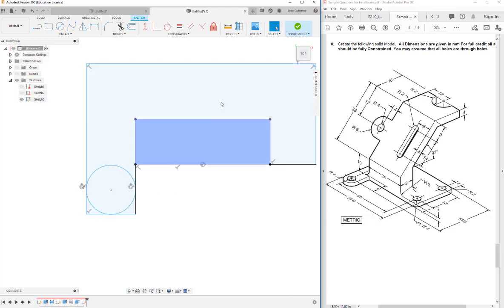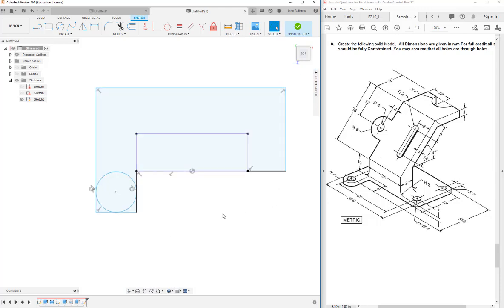It doesn't have to be perfect to what you want to extrude. And actually what we'll see is I'm not going to sketch these corners. I'm going to add those as fillet features after the fact because dimensioning those is going to be too much of a pain. Okay, so now I can dimension this circle again. Now since this is a diameter, I'm going to need to give it 2 times 4 or 8. And then what I do know is that I know the distance from this edge to that circle center. So I'm going to say that is 8.